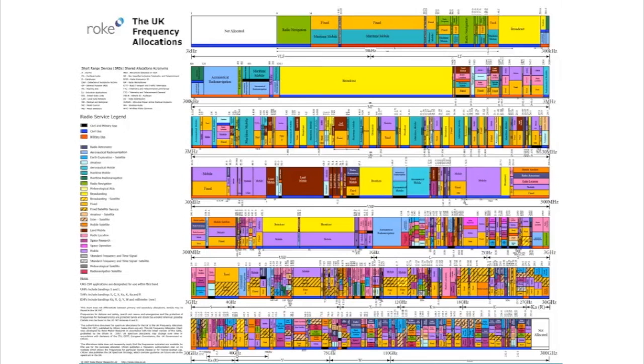So the spectrums that most people are very interested in are the 400 megahertz, 900 megahertz, and 2.4 gigahertz bands. And this is where certification via FCC or CE comes into play. Most component manufacturers have already done the heavy lifting in a wireless product and certified their wireless offerings with various agencies. As a matter of fact, the module I showed you earlier is a good example. They've done the heavy lifting for you, so that's a nice aspect to have.